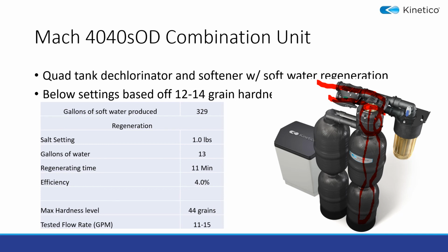The purpose of dechlorinating the water is not only to extend the life of the resin bed in the softener, but also to give us better working water in our everyday lives. Chlorine is an oxidizing agent that will deteriorate softening resin over time, but it will also deteriorate rubber gaskets in appliances, causing leaks. Chlorine is also an irritant to skin. It is used to kill living organisms in water during the treatment process. Unfortunately, chlorine is present in our water when it reaches our homes. Given our skin is our biggest organ, chlorine can potentially dry it out and cause skin conditions such as eczema. Chlorine will also destroy fibers and fade clothes.